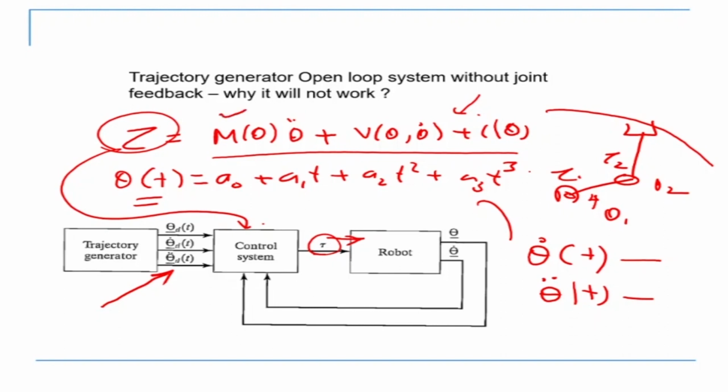Because there are a lot of assumptions when you're computing the mass matrix. For example, computing the exact mass or inertia matrix of the links would be extremely difficult, if not impossible. Why? Because there are gears, motors, encoders, wires, and connectors. So you will not be able to get an exact inertia tensor, because of which there will be approximations, which means that the torque you compute is going to be off by some amount. It will be approximate. So obviously when you apply that torque to the motor, the final trajectory will be a little different. Please note that this looks like a good way of controlling a robot, but it's not possible to control a robot this way.